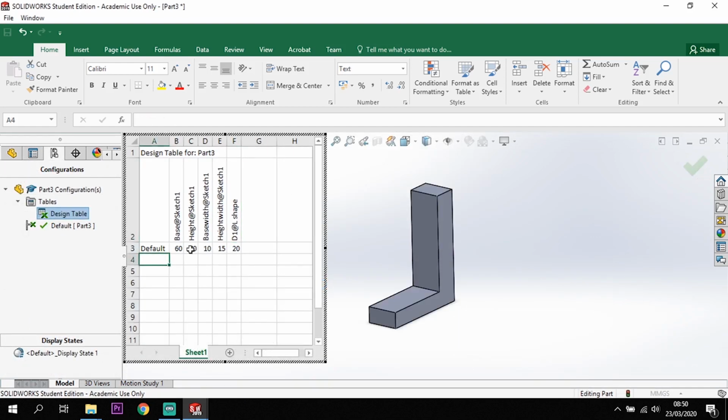Okay, so you can see here then that what's loaded up is our default values across the bottom here, and that's represented with the default at the side, and then we've got our titles that we've put in on our dimensions on our extrude at the end. Now if we want to edit these, we can set our own values down here. So I'm going to put a new title in, so I'm going to call that plus 10%, and I'm going to make a product that's 10% bigger.